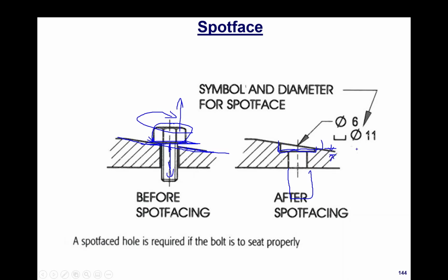Since that is not specified, this is a little more economical to produce. I don't have to have somebody check the drawing and say, well, there's a counterbore there, did the machinist machine at the right depth? No, because in this scenario it doesn't have to be that critical. There's a lot of tolerance in the assembly to allow for a wide variation of this spot facing.